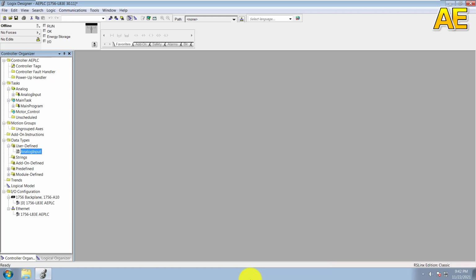If the module is in a remote chassis and the chassis has analog modules, diagnostic digital modules, few output modules, or multiple communication modules, then we don't need rack optimization. If the module is in a local chassis, we don't need rack optimization.